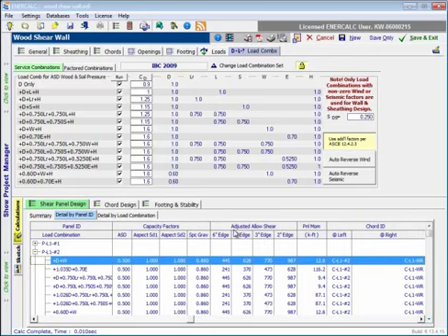The next category is called adjusted allowable shear. So what this does is it takes the nominal shear values for the various fastener spacings for the selected sheathing on side 1 and side 2. It factors them appropriately for the design method, the aspect ratio as necessary, and the specific gravity as necessary, and then it combines logic that's specified in the special design provisions for wind and seismic as dictated for the selected load combination.